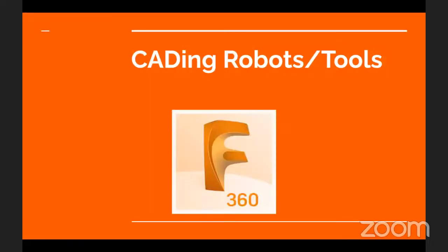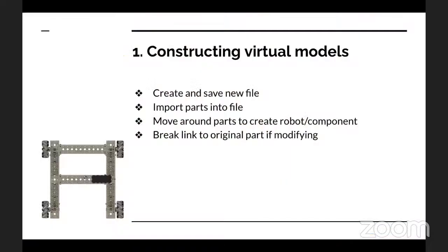First, I'm going to start with CADing robots and tools, so modeling. To create a new model, you first have to create a new file. It's kind of like any document you would have. You create a new file, but then to create your model, you have to use existing parts, such as these C channels on the left, to build a robot. All of these parts you have to import from individual files into a main file, and then you can eventually construct a robot that looks like this. Once you import your parts, like the battery, the C channels, the mechanism wheels, the motors, the gears, you can move around the parts to actually create the robot.